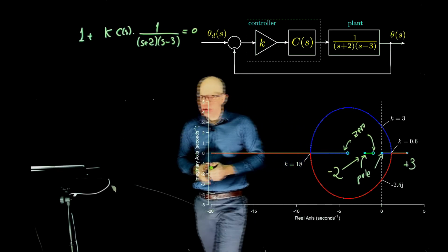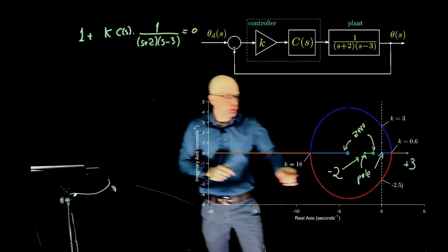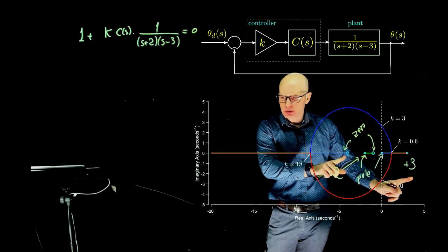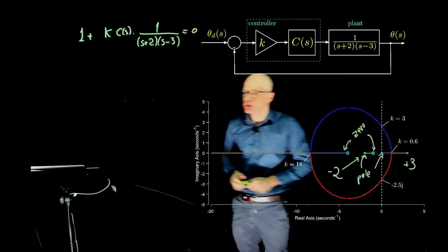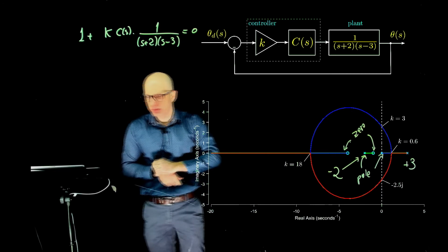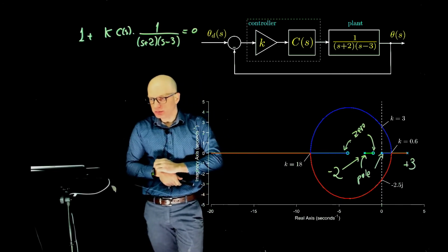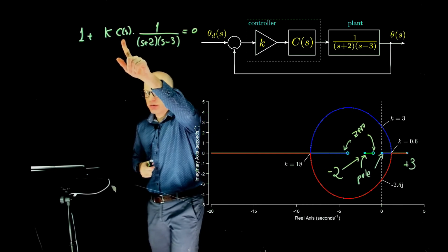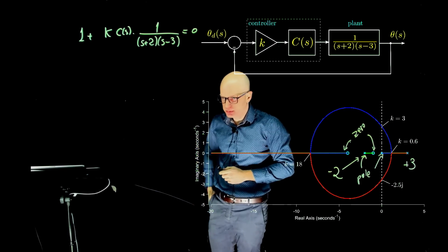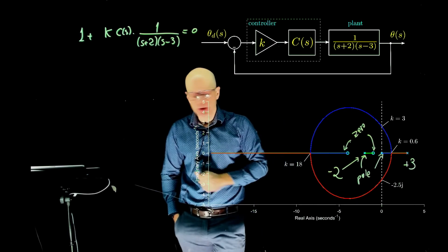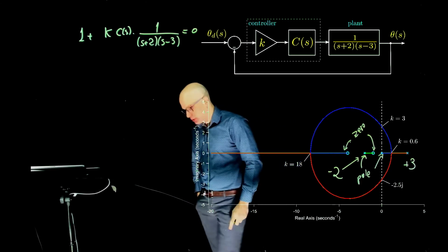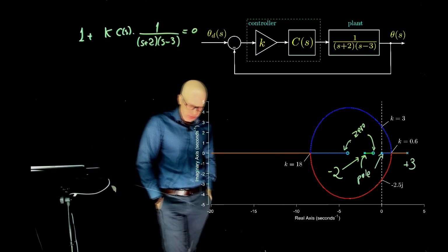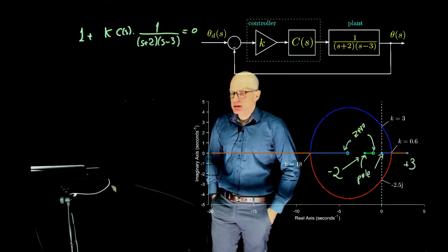Right? So something has changed, because if you only had the proportional controller, then we would have ended up here with only this pole and that pole. Yet now we have a zero here, a zero there, and another pole. Where did those come from? Well, they must have come from C(s). We must have somehow changed the transfer function using C(s) to now add these additional poles and zeros. So it's not a proportional controller, right? Because these extra poles and zeros must have come from C(s). So now the question is, is this a PI, a PID, or a PD controller? Is it a PI? Sorry, PD.